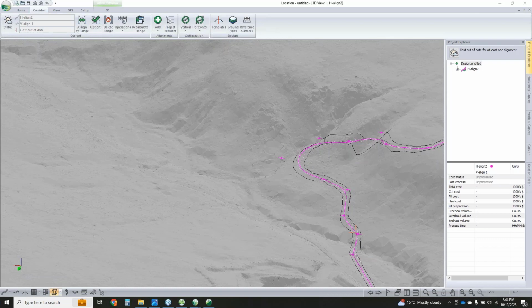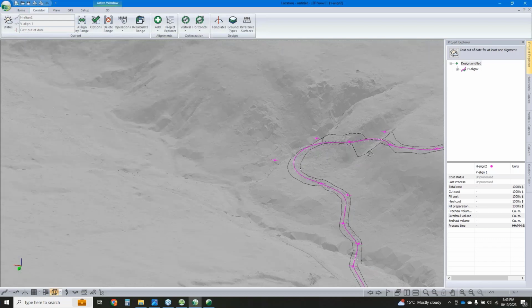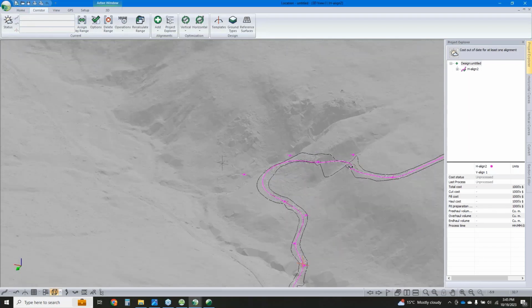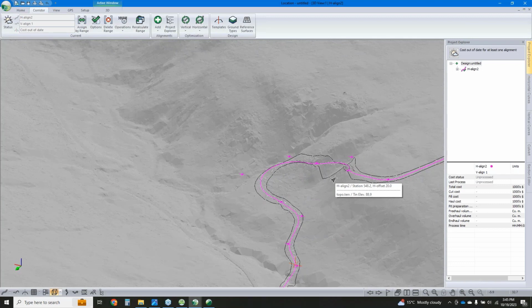That one kind of is what it is. The big thing there was in the traverse side shot, I didn't collect it far enough out. So here, where I fell off the model, it was up here, and where I finished measuring my side shot would have been right on that steep spot, which is steeper than the fill slope angle that I had.